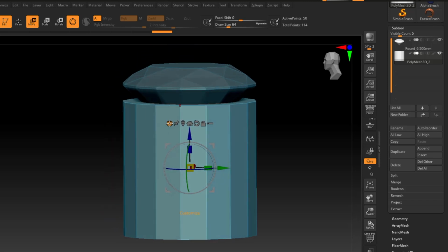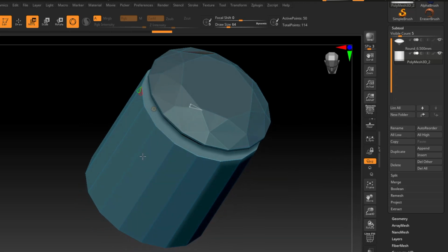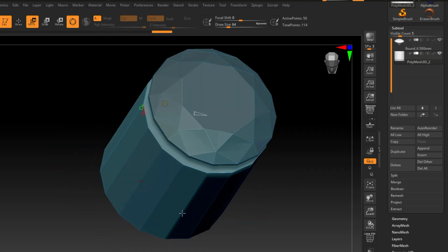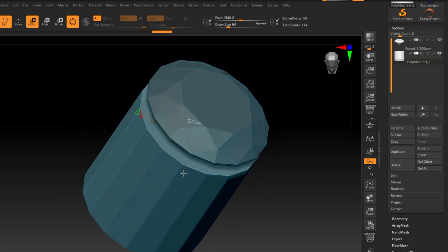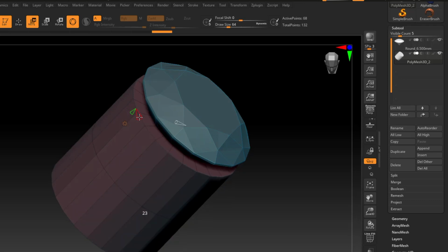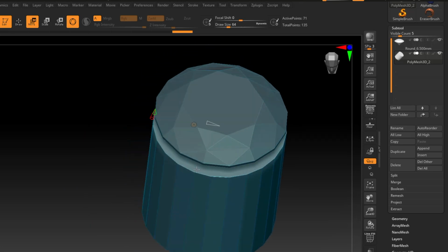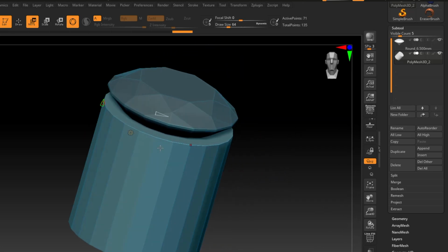I'm going to go back into Customize and go back into my Cylinder 3D. So we can make a few quick adjustments before we move on. So right now, this cylinder is pretty blocky. I want to make it a bit more round. So I've got a red cone here called H-divide. I'm going to click and drag on that just a bit to add a bit more geometry and make it a bit more round. And the reason why we are using this cylinder is because we can actually adjust the inner radius of this one.